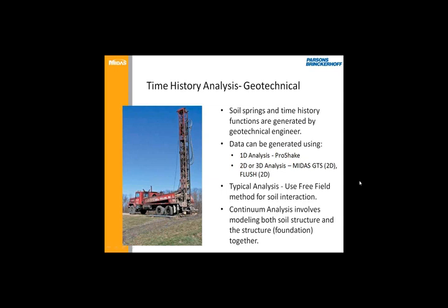Those are also popular. So for a typical analysis, you would use the free field method for soil interaction, and that's basically looking at how the soil displaces based on your rock accelerations. And you don't need to model your actual bridge substructure in this case. With continuum analysis, that involves modeling both your soil structure and your structure together. So from that analysis, you would know the exact forces that are acting on your structure. For my example that I'll be using today, I'll be using a typical analysis. So what we're doing is we're inducing displacements on our soil springs that are interacting with our substructure.